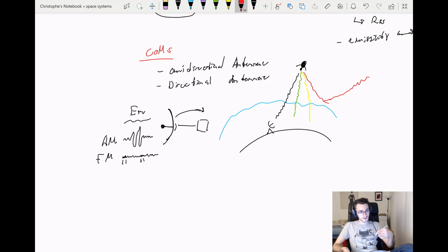That being said, there are different bands out there that are commonly used, so that would be different frequency bands. There are things like S-band or X-band, which have different bandwidths, and you can send different throughputs of data through each of those. Those are regulated, so you can look. I'll post a link down below to some of the documentation for communications regulation with regards to satellites.